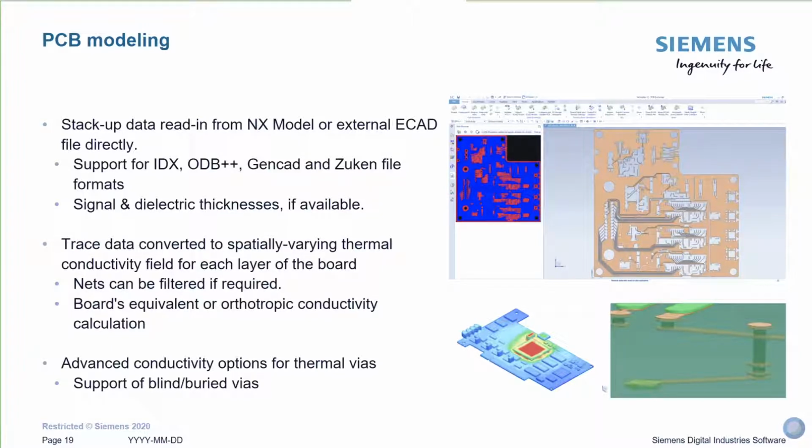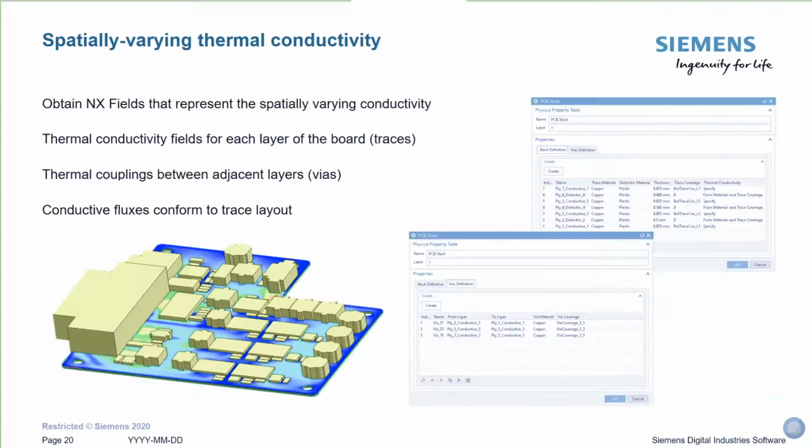So if you have thermal vias that have thicker plating, this can be specified for specific vias based on the pad stack name. And you can also decide to fill certain vias with non-conductive material, conductive material, again, based on your requirements before the analysis.